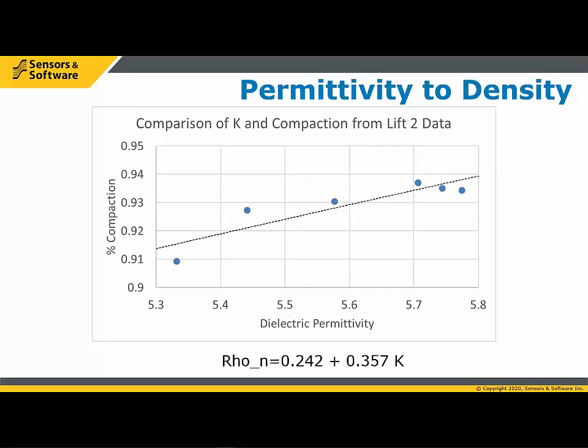We're building up experience with doing that. We first went down the rabbit hole of trying to do a lot of correlation between cores and permittivity measured with the PDP, and we found it was really hard to get that data. Invariably on a stretch of line or road, you'd have a dozen cores at most, and it was hard to have confidence in that. There was a lot of variability, because we thought people weren't necessarily getting the cores at the right locations, so it was a disconnect between one set of measurements and the other. So we've had challenges. Getting coring done close to when you do the measurements at high and low spots was probably going to be as reliable as any other approach.